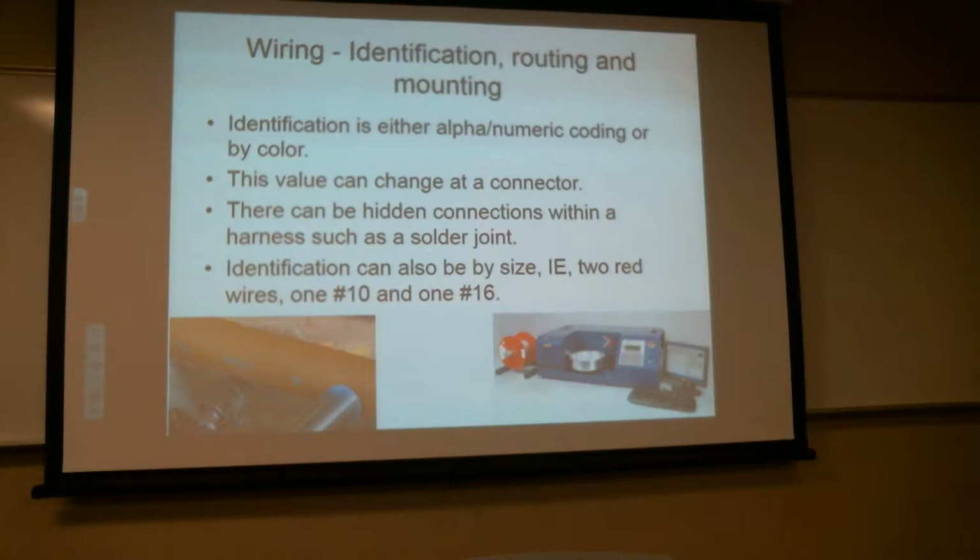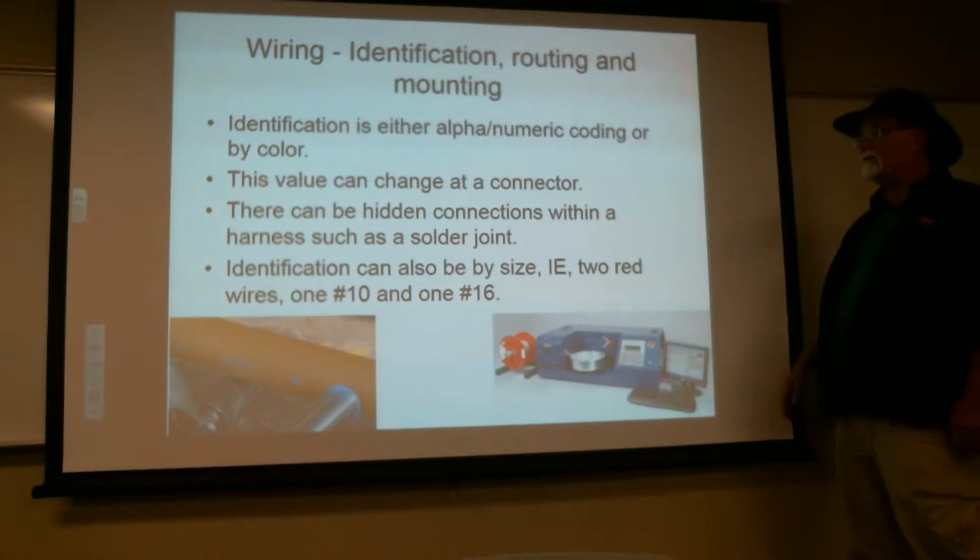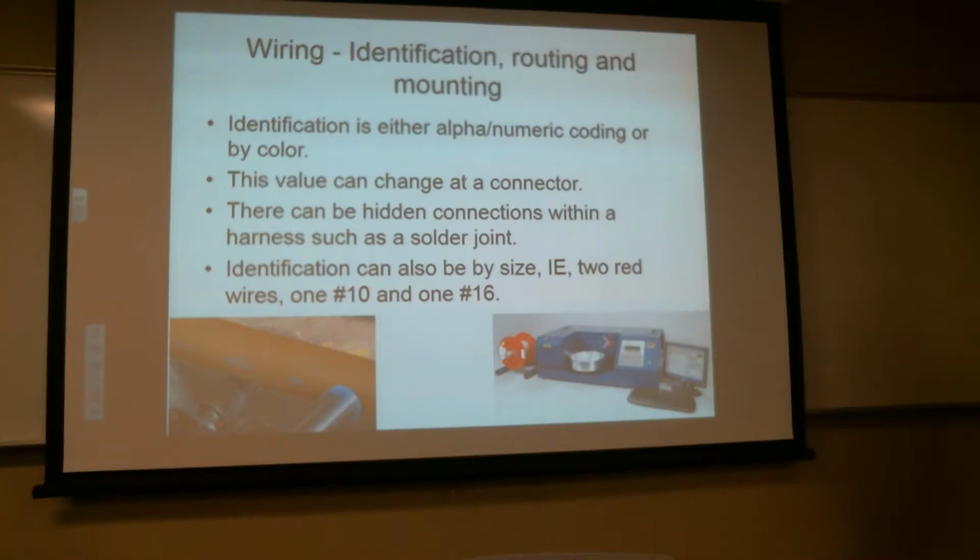So there you are with a connector and a wire heading out that's purple green, but you go to the other end of the harness, and no matter where you go on that harness, that purple green wire doesn't come out. Like, where did it go? And nothing you read says anything about that particular wire. Now you've got some problems. And unfortunately, sometimes the only way to find it is to start splitting harnesses.